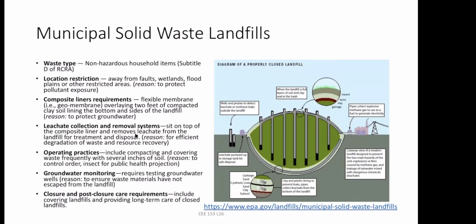And then you also have to compact the waste to minimize the space. You have to keep adding some kind of cover in between so that you don't have rainwater going in. And then you have to monitor the groundwater to ensure the landfill is not polluting other systems. At the end, when you finish the entire landfill, you close it and make sure you have a very compacted topsoil and a gas collection system so that you can continue to produce energy over time. So that's why you see this energy.